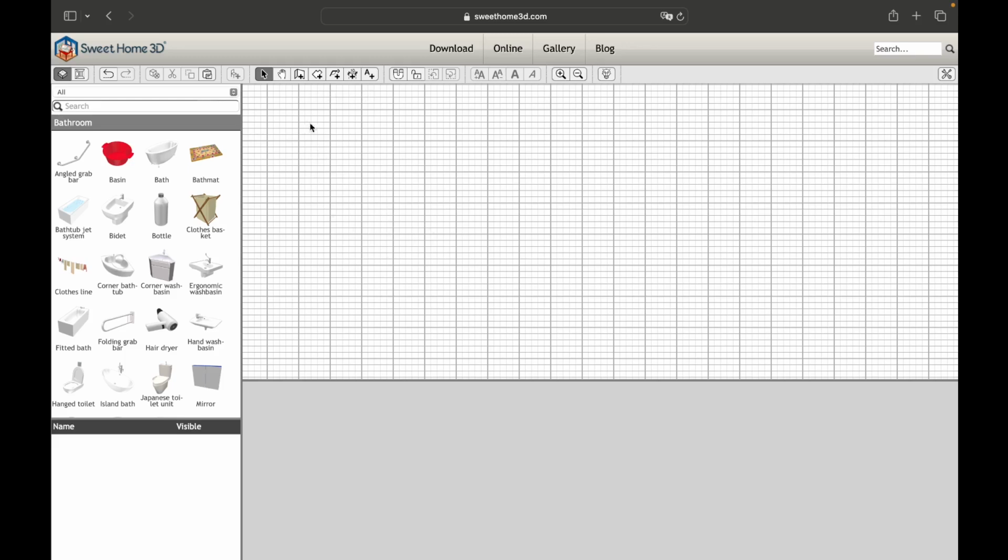To use the command, simply select the Create Walls tool, position yourself on our workspace, and click with the left mouse button to establish the beginning, and click twice to establish the end. To create multiple walls in sequence, simply click the left button once and double-click to close. This created room has no floor. In fact, the internal surface of the walls is the same as the external one.